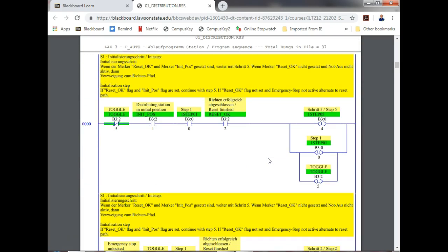And you can see this guy predominantly uses B3s, which is what? Internal coils, right? And these use latching and unlatching. Y'all understand latching and unlatching? So once you latch, it's going to stay latched until you do what? Until you unlatch it. That makes sense?